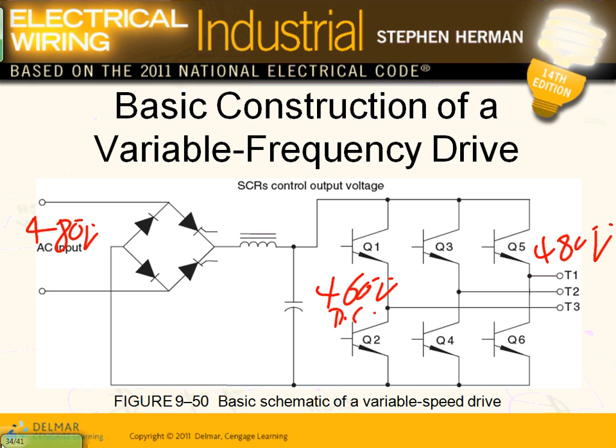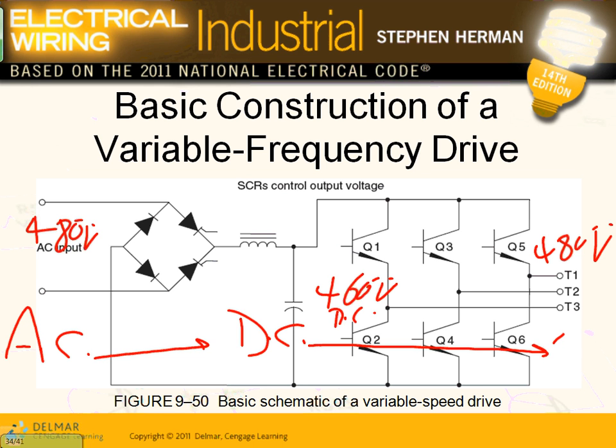First, they converted to DC. We went from AC, which we care less about, to DC. That's where we do the speed control. And then we spit it back into AC because we need to tie it to an AC motor. Can you guys see the process in between? You have to go through the stage of DC so you can speed control the voltage. Then with these diodes, they cut the frequency to recreate an AC from a DC.